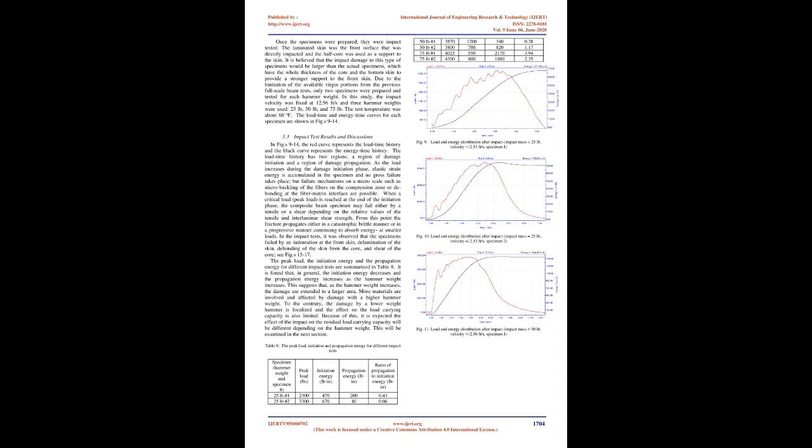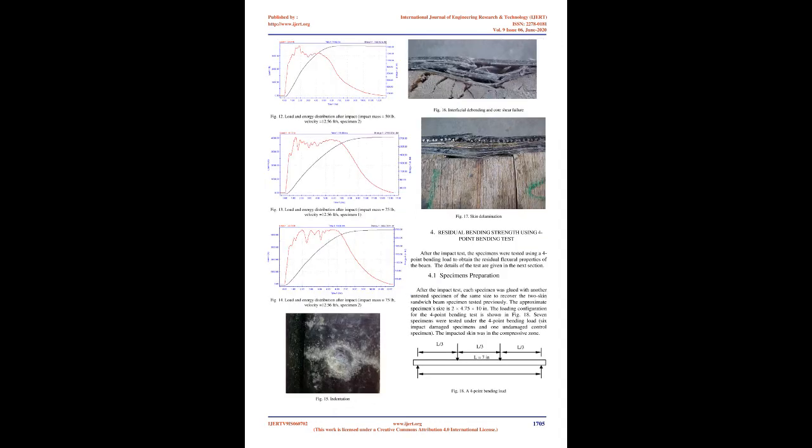What makes things even worse is that low-velocity impact damages usually avoid visual detection. Most of the time, only a small indentation can be identified on the impacted surface after a low-velocity impact. However, significant delamination, matrix cracking, fiber breaking, and fiber/matrix interfacial debonding may have been produced inside the specimen and on the back surface. A low-velocity impact is not uncommon. A dropping of a tool during a routine inspection characterizes a low-velocity impact.